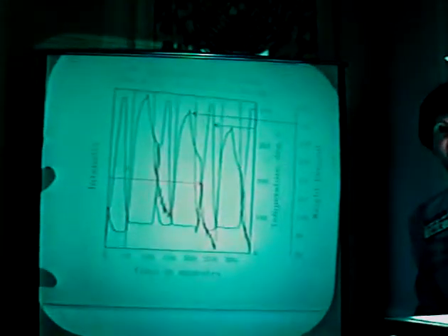Yes? How are these materials regenerated? Basically, just heating them up to 200 degrees. But then you reverse what you tried to accomplish. Well, no, what you're trying to accomplish is to remove the NOx from the combustion stack and possibly then concentrate it in a separate stream, which could be dealt with, say, for chemical utilization, for production of nitric acid.